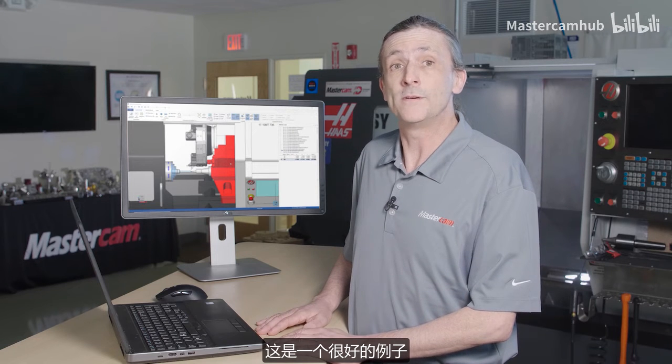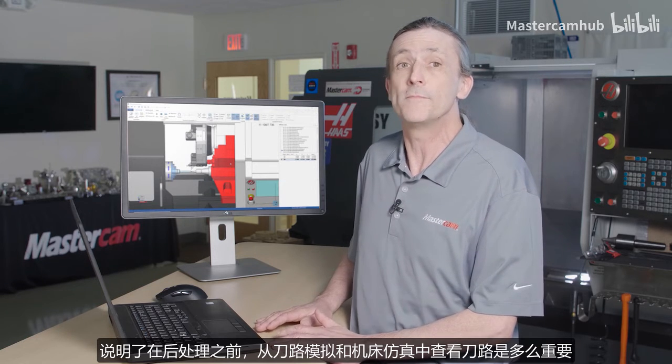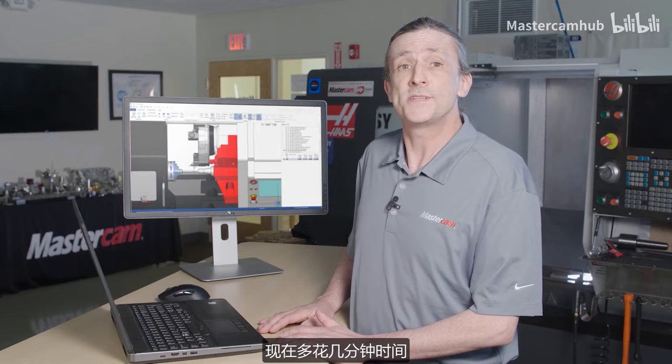This is a perfect example of why it's so important to review your toolpaths and backplot simulation before posting them out. This issue would not have shown up in backplot, since it's a collision between machining components, which backplot isn't capable of displaying. Taking a few extra minutes now can save you from ending up with a broken tool, a damaged machine, or simply having to diagnose an unexpected stop.